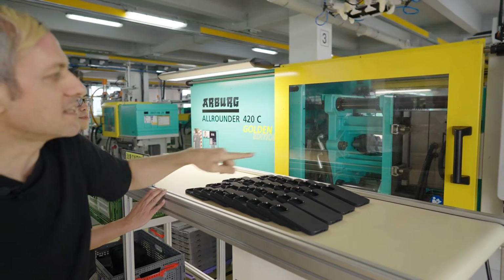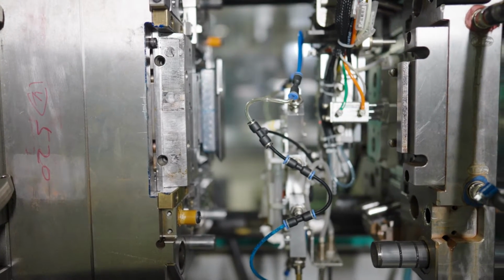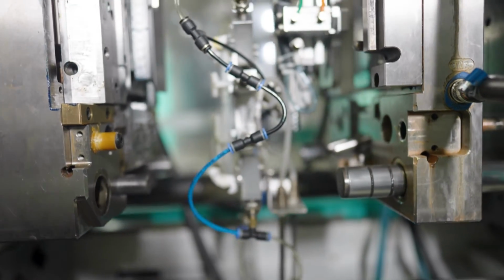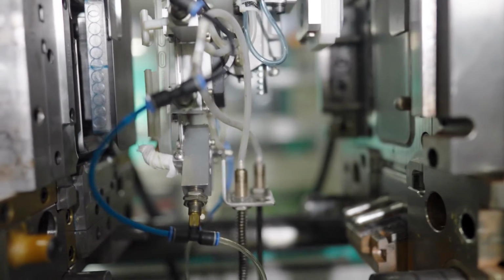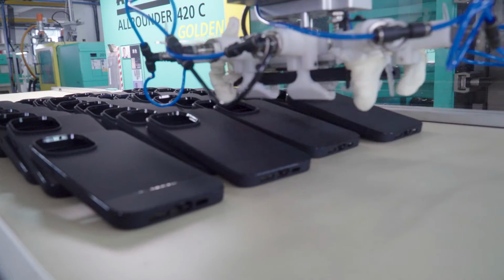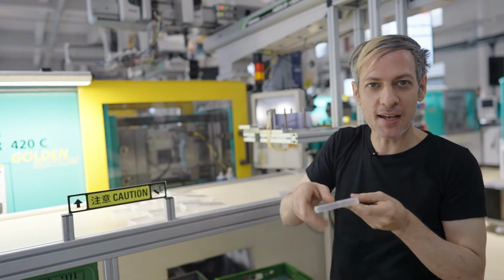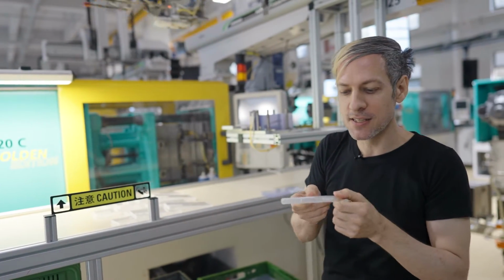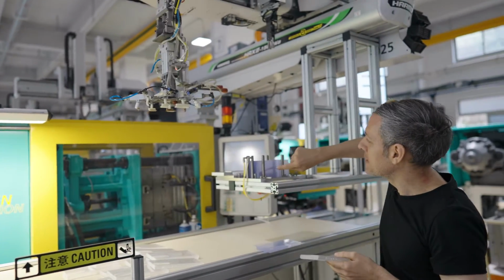And here you can see the phone case being made. The mold is pushed together by a giant hydraulic ram, and then the plastic is injected into the mold, and after it cures or cools, the mold comes apart, and now the robot arm comes down and grabs the phone case. Unique phone case. It's got a rigid back and soft, flexible sides, and the way they make it is they keep the rigid material here.